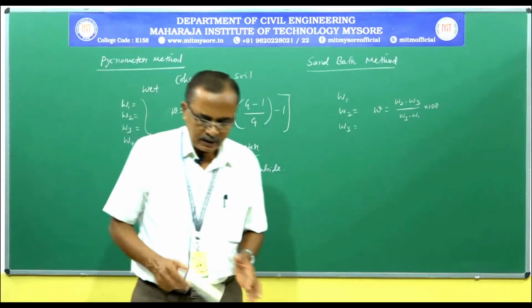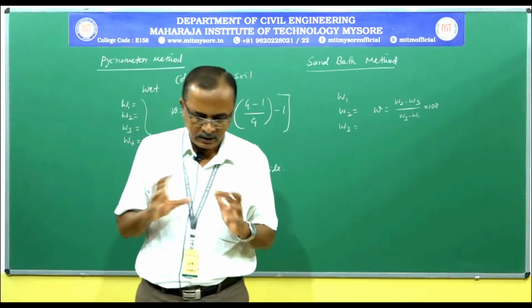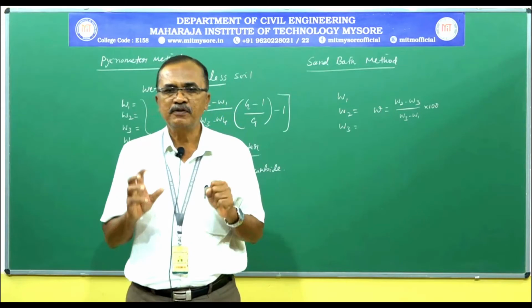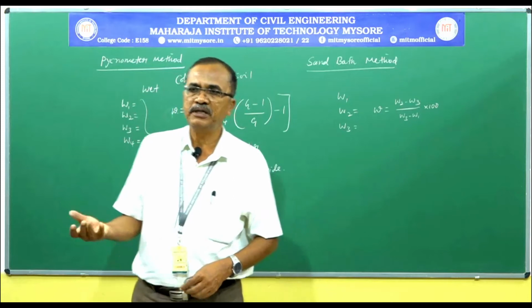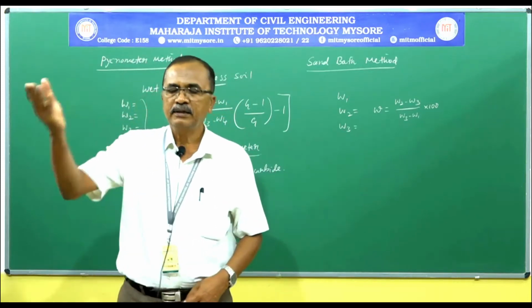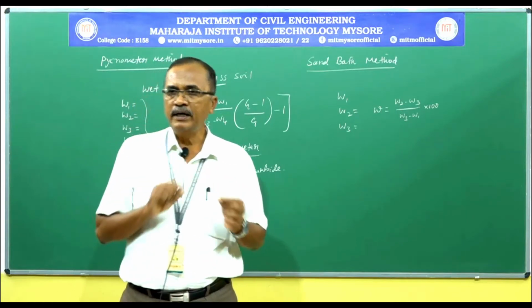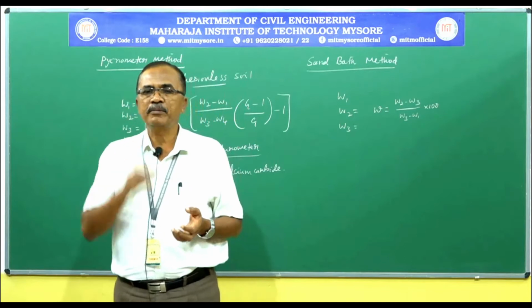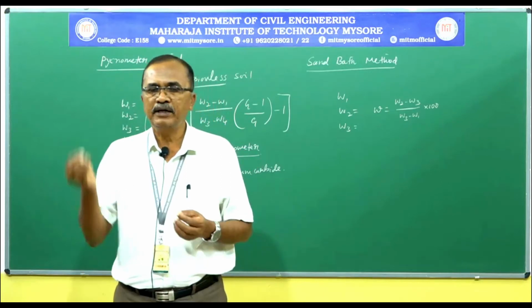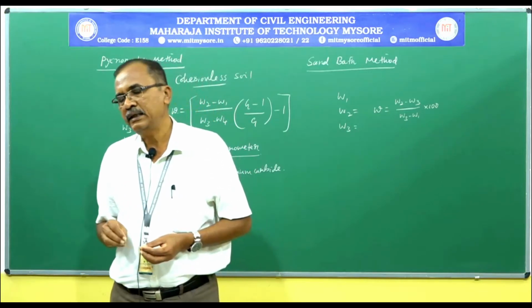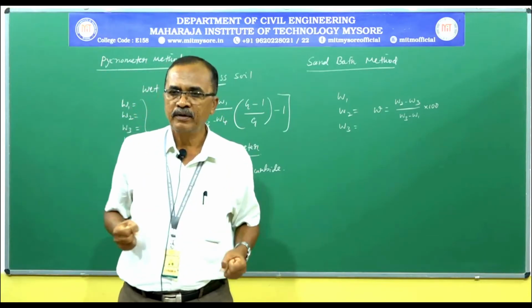The rapid moisture meter is portable equipment. It resembles a thermoflask, which we use for maintaining the temperature of water, tea, coffee, milk and so on for a longer duration of time. The soil whose water content is required is placed in the rapid moisture meter, and the required quantity of calcium carbide is placed inside it, and it is vigorously shaken.